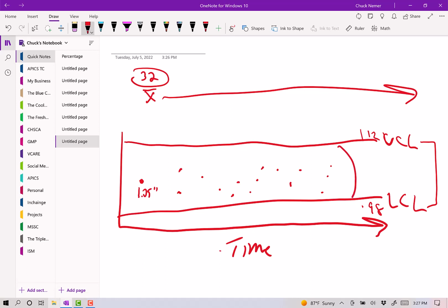So this is the range of normal variation. And if we get a measurement outside of this range of normal variation, maybe up on top here, we would stop the process, isolate the parts, call the engineer down, have him or her look at it, and decide if that was just a one-off and we should keep running, it was just an odd situation, or is it tipping us off to something else?